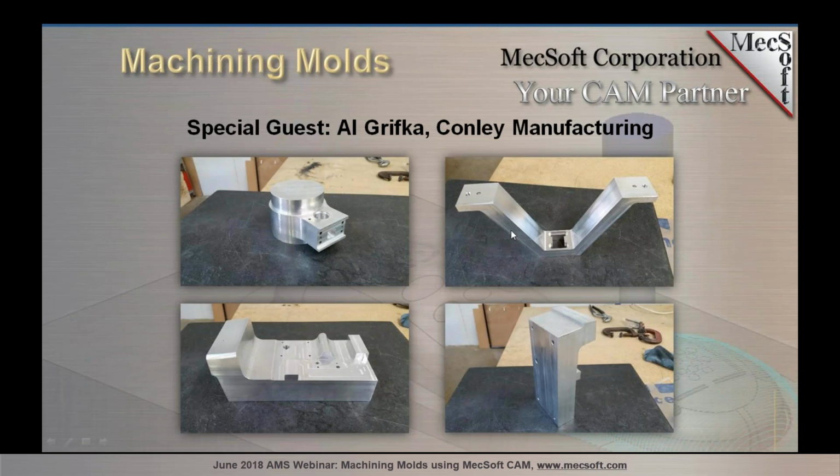This here would be like a strapping fixture. So there's 2 dowels for location, and there are 2 tapped holes to hold it down. That would most likely be flipped upside down to hold some type of beam or hold something to the side of the plane or the inside. There's some countersinks and some grooves down in here where there'd be a feature that would stick through on the other side for like a hoist ring or something of that nature.